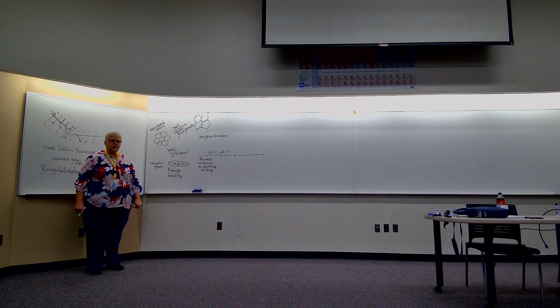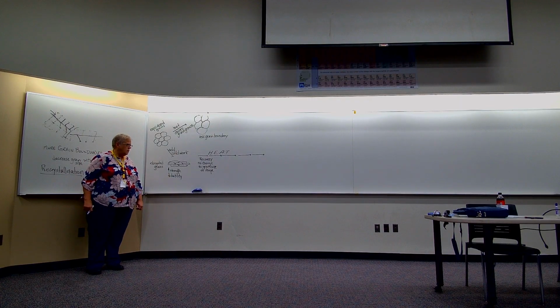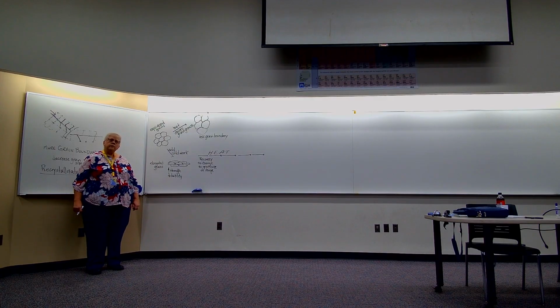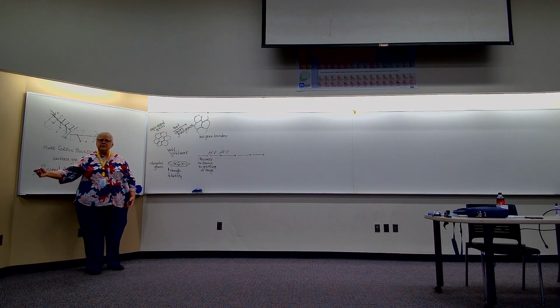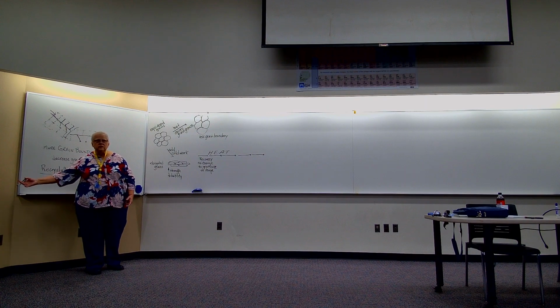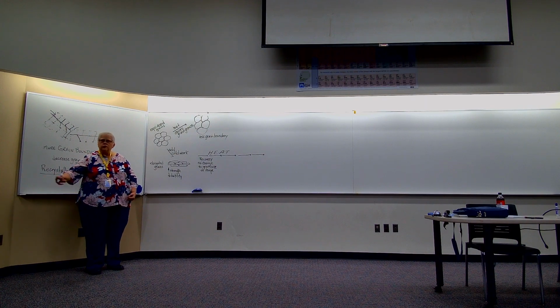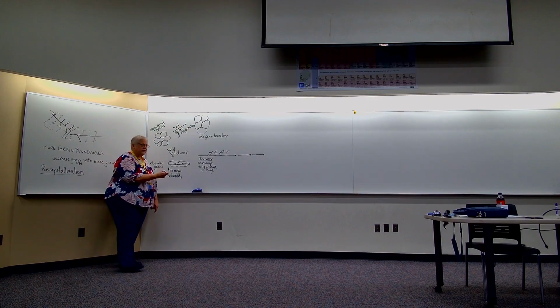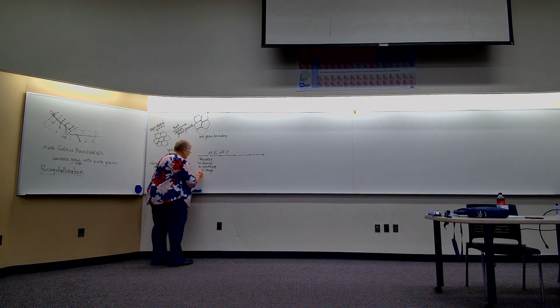This would be the step of annealing when we were doing those examples of cold work and trying to get it down to a certain size. And we would have to anneal so that we could do more cold work. That's kind of like what happens here. There's a reduction in the number of dislocations.